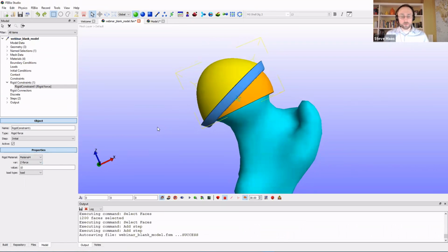I just mentioned that usually you want to have multiple time steps so that you can ramp up the force. So how do you actually do that? Because we just entered the value 10 here. Well, what happens in the background is that in many of the loading conditions, boundary conditions, and constraints, there is also what we call a load curve associated with it.